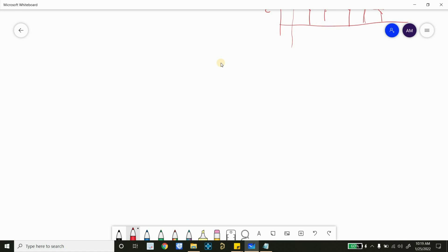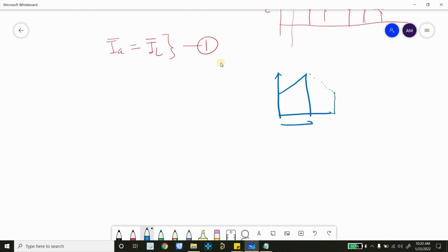Firstly, let's talk about the on state. When we use the first expression that we have already calculated, the amount of current flowing through the inductor will be I_L, or the average current. This will be our first expression. The waveform will be for T on. It will be something like this, right? And this part we will not see on our scope. So this will be the time to charge the inductor, and this is the total time period, which we'll represent with T_S.